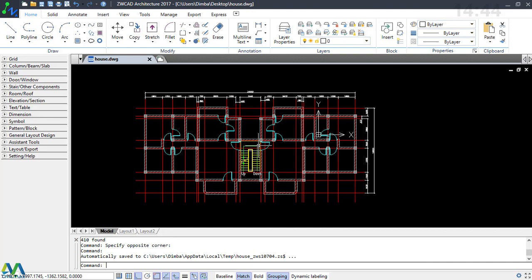4th floor. Now this drawing plan, I want to convert this into PDF. Then from PDF, I'll import the PDF into Tekla Structures. Then I'll start modeling the structural parts of this, and later on detail the RC, and later on give RC details. Now straight away I'll get started here, and converting this into PDF shouldn't be a very big issue.